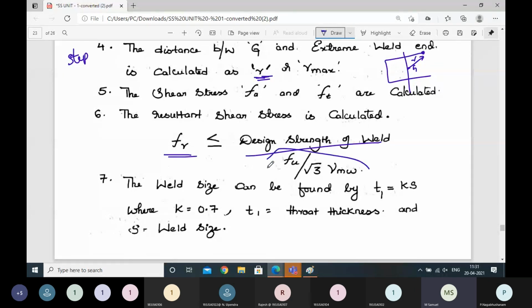Okay. And of course, for a shop weld we take 1.25, and for a field weld we take 1.5. And if you take care of that value substitution and you check this, if it passes, it is safe. Okay, that is good. You can leave it there.